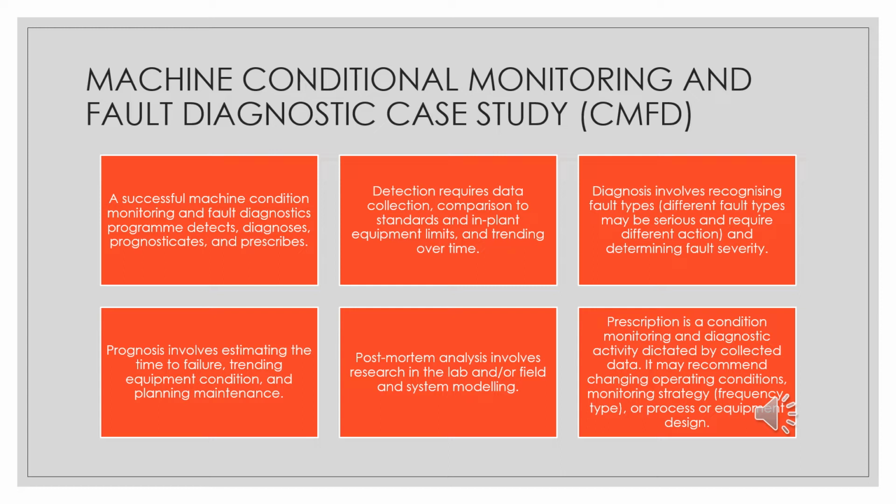Post-mortem analysis involves research in the lab and or field and system modeling. The last one is prescription. It is a condition monitoring and diagnostic activity dictated by collecting data. It may recommend changing operating conditions, monitoring strategy, which is frequency or type, or process, or equipment design.